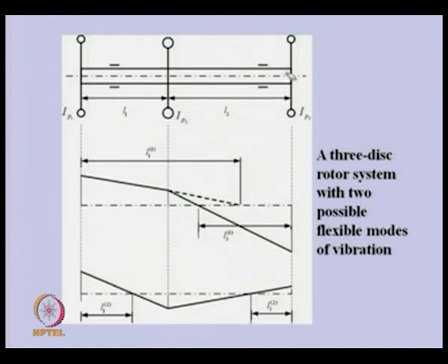As such, this particular mode has no practical relevance, so we will not consider determining that natural frequency, but we are interested in obtaining the 2 other natural frequencies, which correspond to flexible modes. For this flexible mode you can see this is a possible mode shape, in which these 2 disks are having